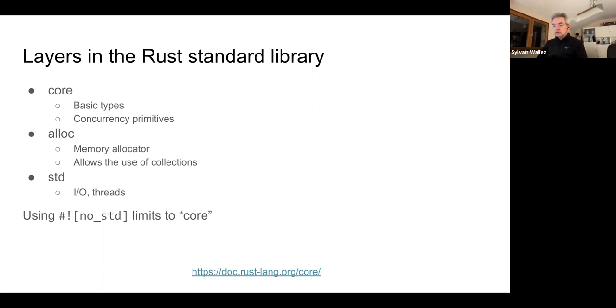That is all those small tiny wrappers that give typing, and on top of that, you can add, when you have enough memory, an allocator, and then suddenly all the collections become available. But in embedded systems, you have to use the memory allocator very carefully, because if it goes out of hand, then your system will crash.